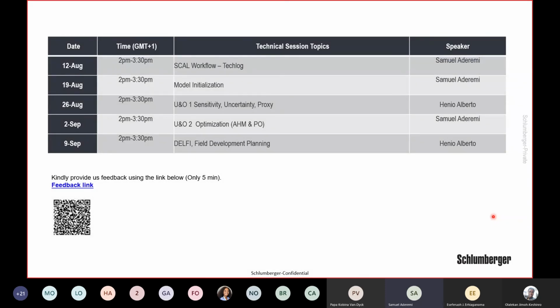You add one more point to that table that shows a very large change in pressure but a small change in that value. So it will be relatively close to that horizontal, constant behavior that you want. It's a way of tricking the simulator to make that happen. If you have such a table, send me an email and I will show you how to do that separately.